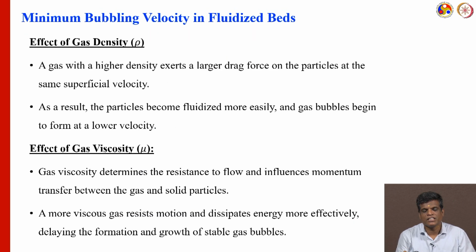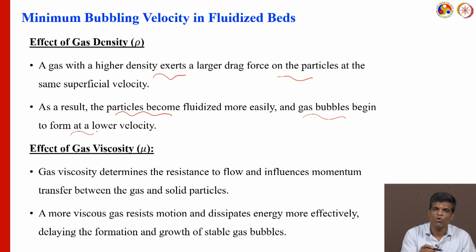Then the effect of gas density. A gas with a higher density exerts a larger drag force on the particle at the same superficial velocity. As a result, the particles become fluidized more easily, and of course the gas bubbles begin to form at a lower velocity.